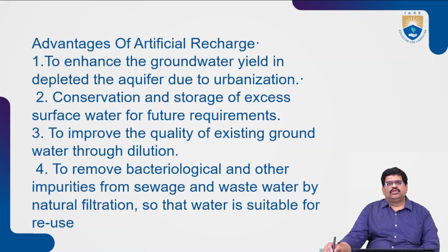So to improve the quality of the groundwater through dilution, and also to remove bacteriological and other contaminants, sewage water cannot be allowed, and fresh water is suitable for recharging. Why? Because if already contaminated water is allowed, the contaminated water will again contaminate the purified groundwater. So that is the main reason. So some purified water can be used for groundwater and artificial recharge.